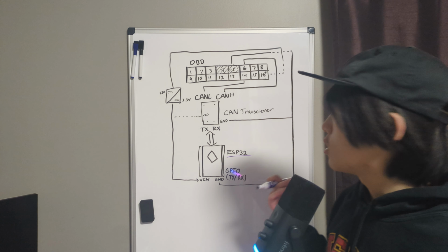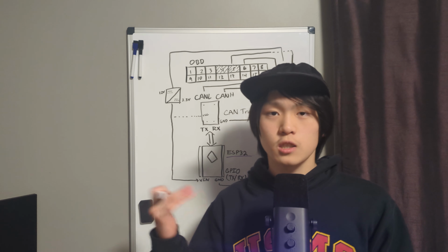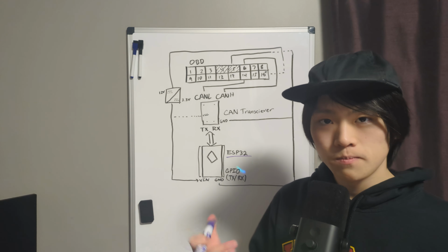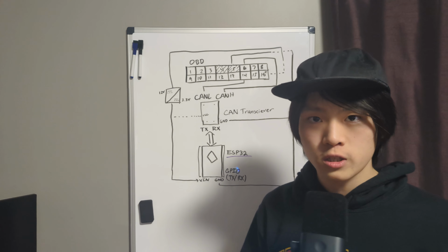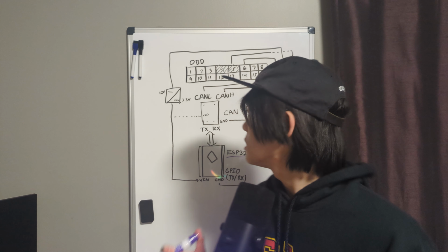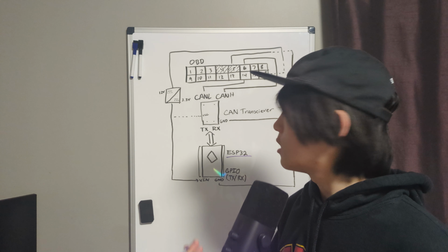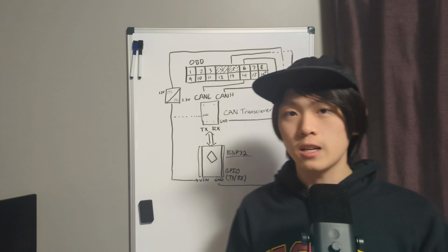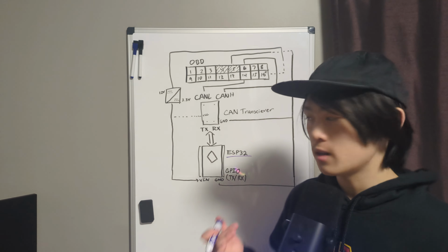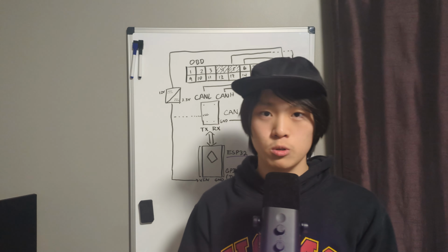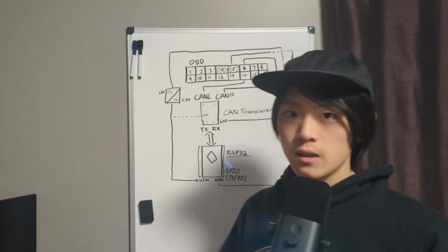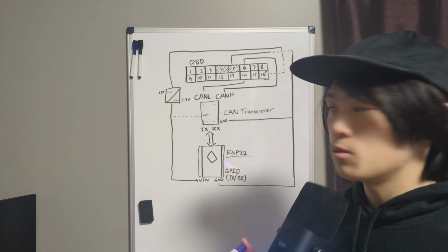But it's not only for diagnosing, but also for gathering data. For example, the OBD port can provide information such as speed, fuel level, probably temperature, revolutions of the engine. So with all this data, we can collect it, right? We can transmit this to the ESP32 and save the data somewhere, or with the ESP32, because it is a wireless module, it can operate with Wi-Fi or Bluetooth. We can transfer it to an app, to a phone, or to a computer, or to an SD card. Honestly, anything. It's very flexible.